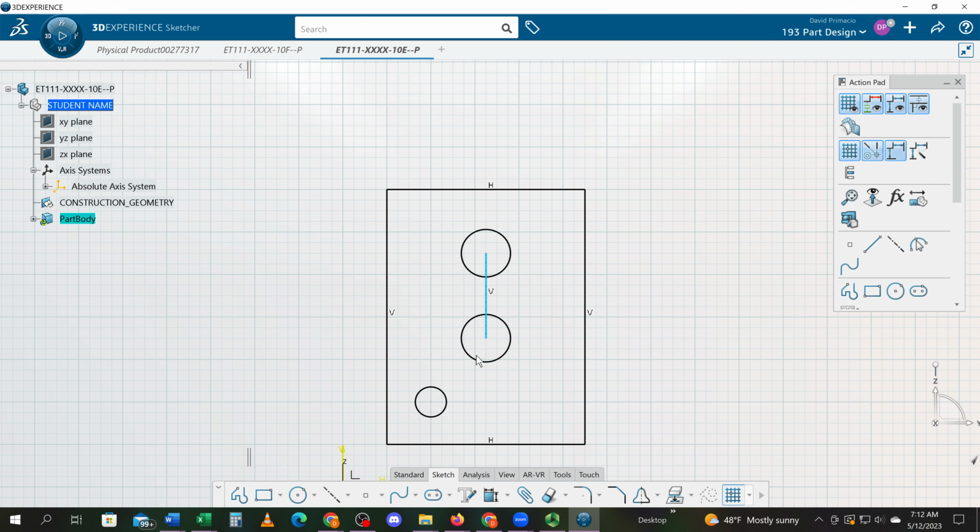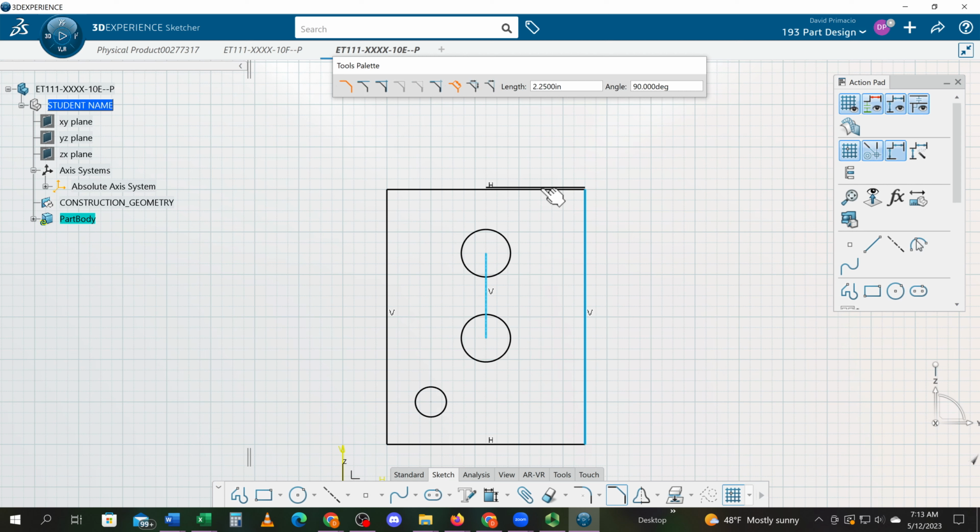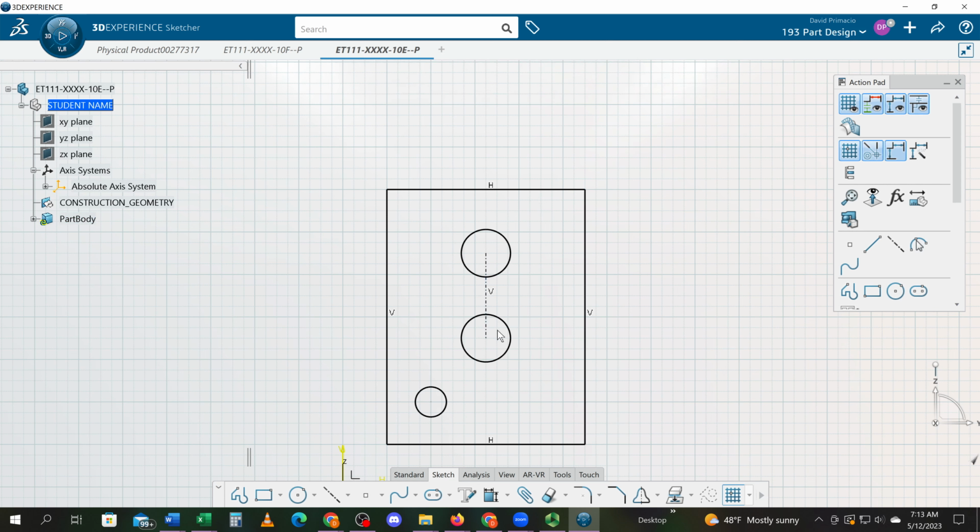I'm going to go to chamfer and select this line. Make sure I do this one. This line. Whoa. Careful, I had that line highlighted already. I was trying to chamfer between the two parallel lines. Didn't know what to do. Under chamfer, I can just create a box around this corner and then click over here somewhere.